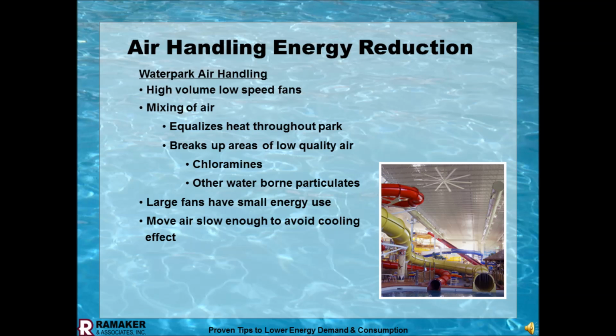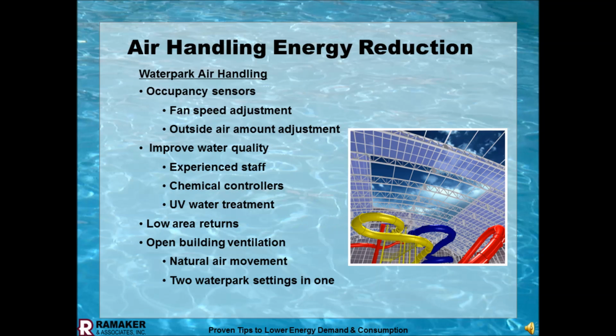We're balancing the humidity out with outside air coming in, mainly in the cold temperatures. Outside air has such a low humidity, but we were still doing the sledgehammer approach with 100%. What we've been doing on our most recent projects is putting in the occupancy sensors, doing the VFD to reduce the fan speed, and now we're also cycling some air back in.